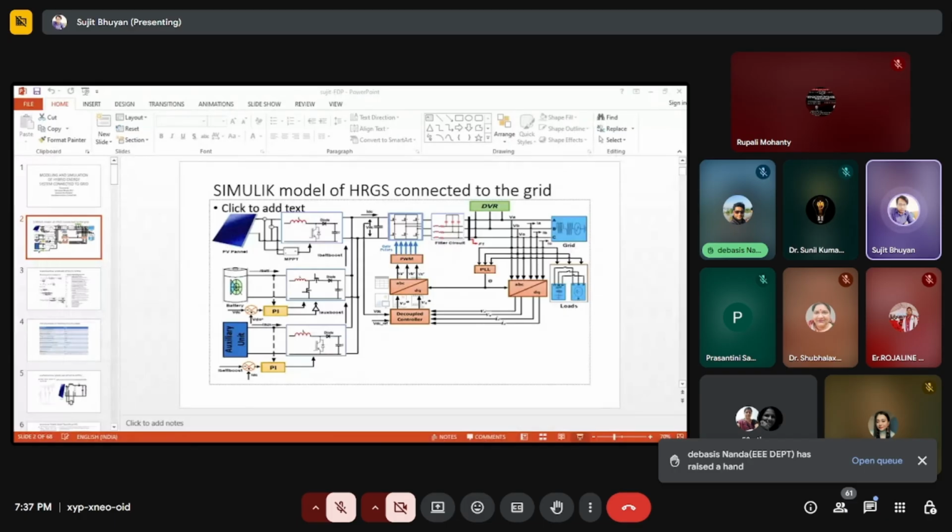I think all of you know the types of triggering of switching devices: forward triggering, gate triggering, dV/dt triggering, light triggering, and temperature triggering. In industry, we use the gate triggering method because it is easier, and pulses are required to trigger the switches. If you remove the pulses, the switch is closed and your connection is not harmed. But in forward triggering, we have to give some amount of voltage, after which the junction breaks down and current flows. Here basically we have used gate triggering. Just remember that.